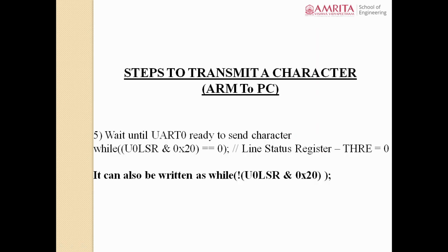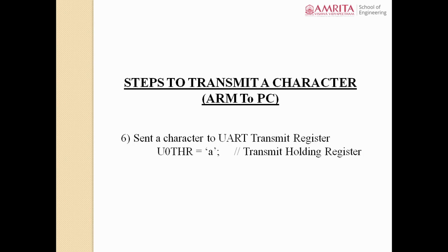In step number 5, we will check whether UART0 is ready to send a new character. So for time being, we are skipping this step. We are going to the next step. We will discuss it a little bit later. So in the sixth step, what we are doing, till step number 1 to 4, we have done initial configuration for the UART peripheral. After doing the initial configuration, what you should do, you need to transmit the data